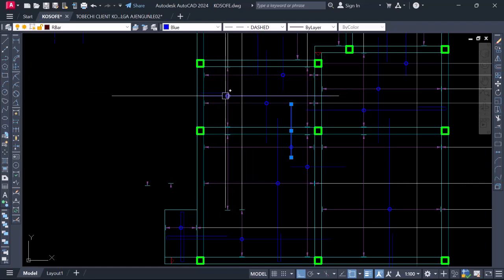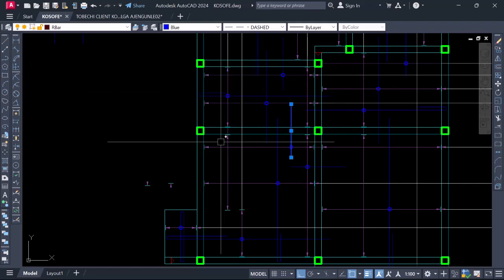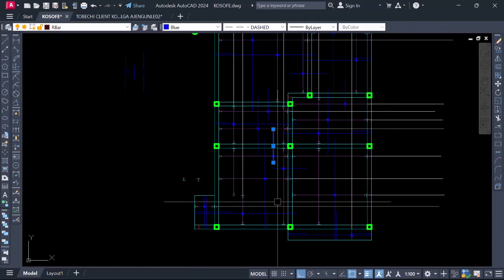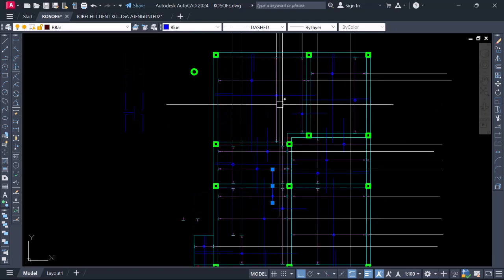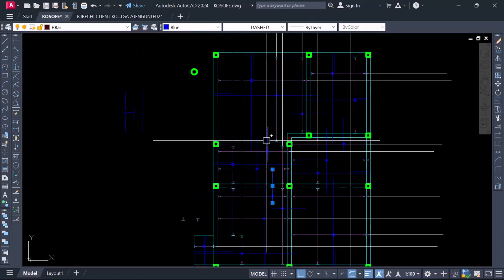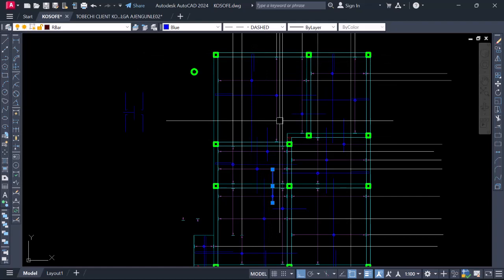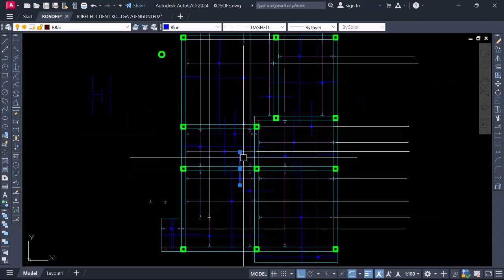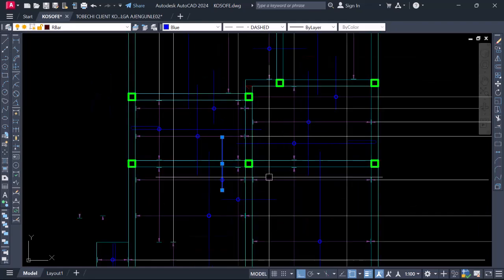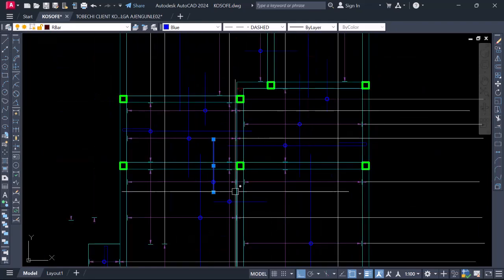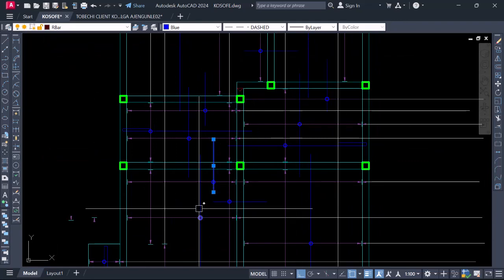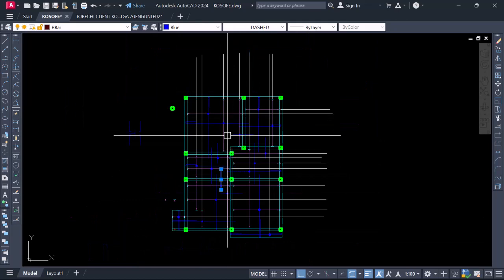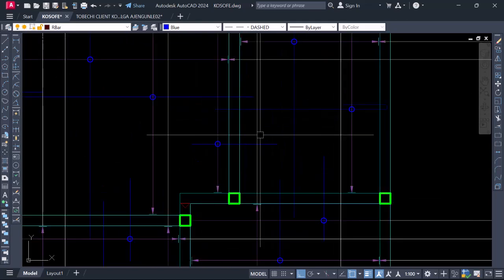This is how we're going to read it. We're going to read this reinforcement as crossing both panels, and also this one cutting across both panels. The one having an end-to-end arrow, identify that you are having just a single direction, a single panel. So when you have one reinforcement cutting across both panels, you have to have an arrow showing that there's continuity in that reinforcement. In this, we have successfully detailed our top reinforcement and our bottom reinforcement.